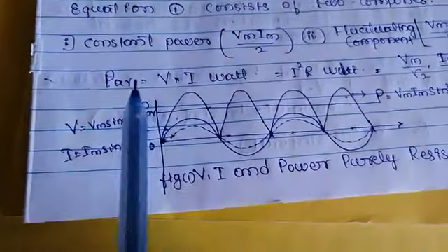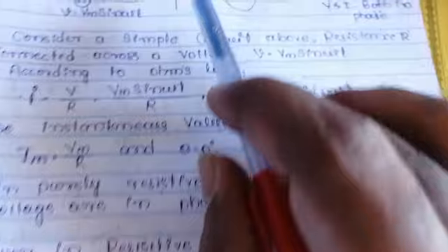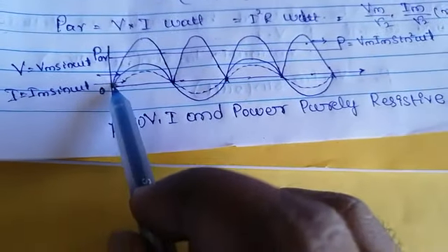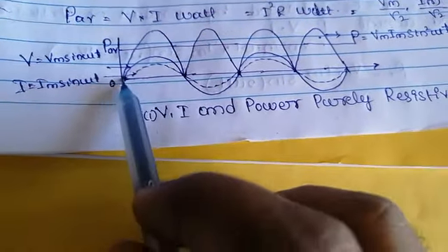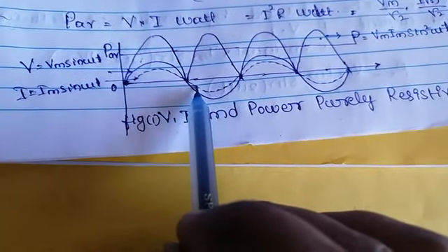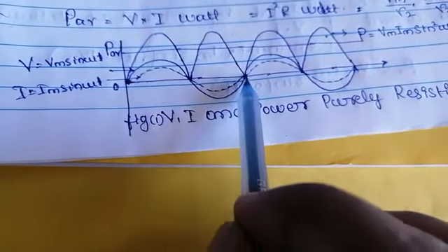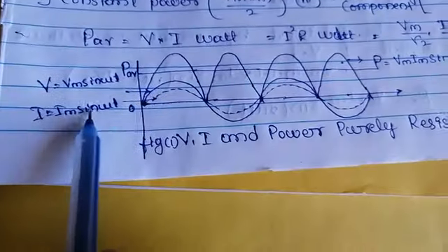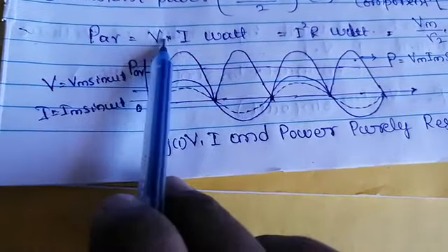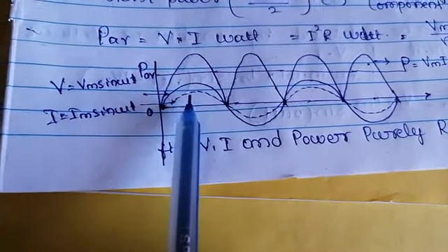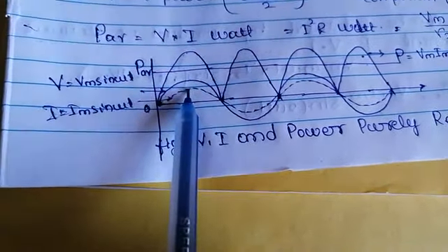Therefore in waveforms, see here, this waveform we have studied, it is a current waveform, it is a voltage waveform. Same here we have to draw. This is the voltage waveform, the dotted one is the current waveform. It will be the same in the negative half cycle, because it is resistive, both are in phase. What happens to the power? Power means V into I, both we multiply. It is positive, it is positive. For example, it is 2, it is 2.